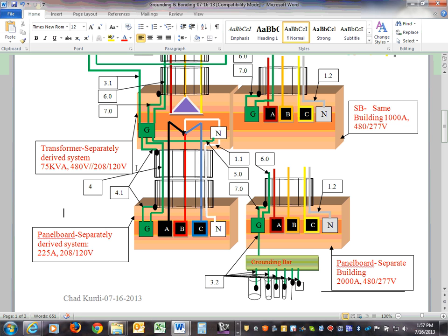number 4, which is a wire inside the conduit. In either way, though, if you pull the wire, you still have to put the little dot here and bond the conduit. That acts as your supply side bonding jumper. Any comments, guys? Any questions about the supply side bonding jumper?